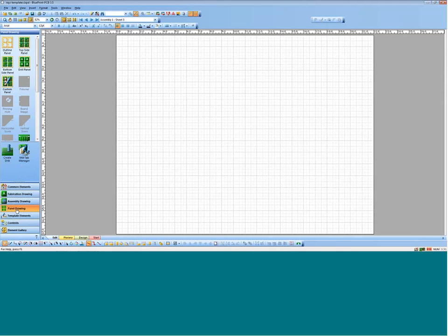And panel drawing is a documentation issue. It's not really a CAM issue. It's something that we need to document properly, and that's the most important part. The tools that we have currently force us to go through a CAM tool to do this. We have to go in, do a step and repeat, then we can output the step and repeated data, but then we probably go into a mechanical tool and add things like mill tabs. Unintelligently, by the way, they're just pictures of what a mill tab should look like.